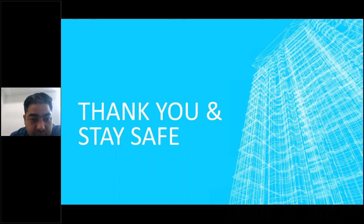All right. Thank you for that. Glad you enjoyed the energy efficiency presentation. So for the boiler, again, efficiency comes down to how much is the heat output by heat input, right? There are ways where we can optimize the flow of the oxygen to the endpoint, as well as the pressure variation across the boiler itself. By tweaking these points, we can actually optimize the boiler. And again, it comes down to what is the final end result and what is the load required or expected across the boiler. So looking at this, we can actually optimize it.